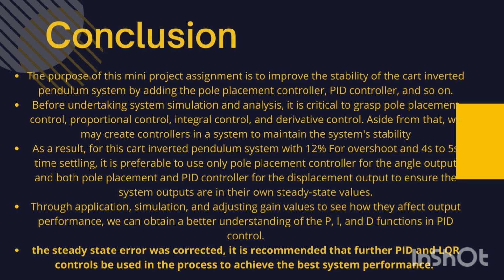Through application, simulation and adjusting gain values to see how they affect output performance, we can obtain a better understanding of the P, I and D functions in PID control. Although the steady state error was corrected, it is recommended that further PID and LQR control be used in the process to achieve the best system performance.